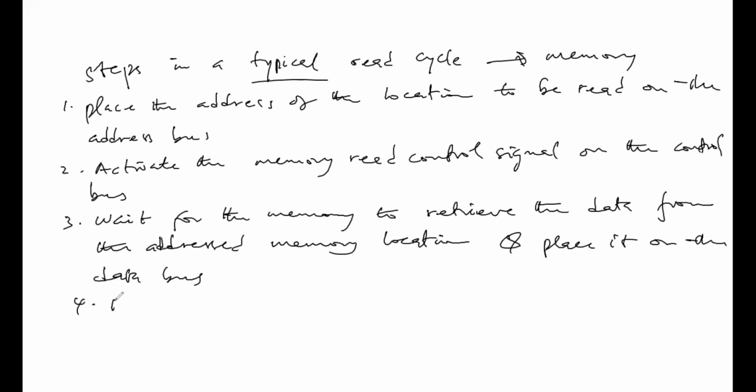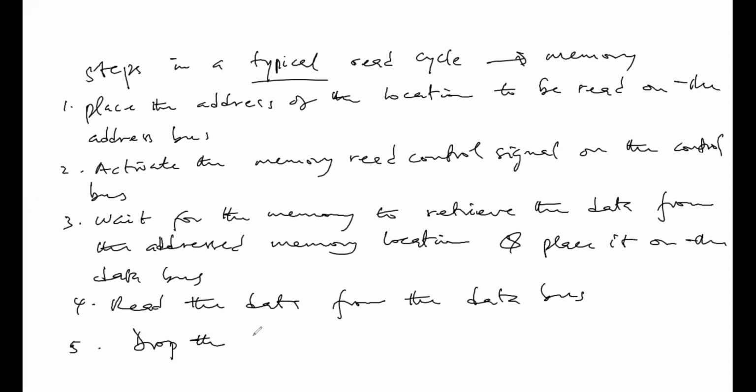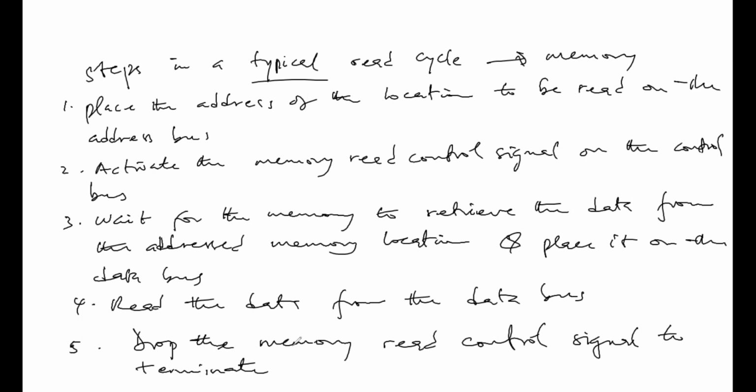Then you want to read the data from the data bus, and then finally you drop the memory read control signal to terminate the read cycle. That's a typical read cycle algorithm.